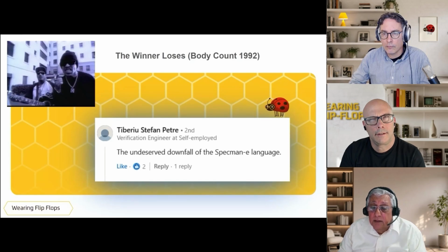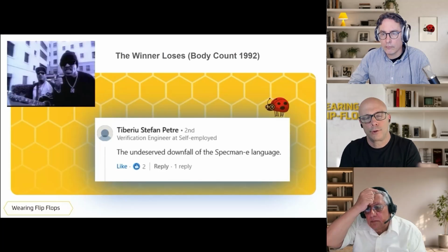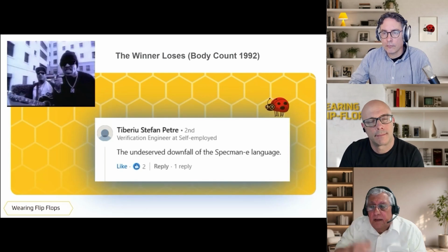Okay. And if we're talking about UVM, what do you need to do there in order to reach the same capabilities? There is a capability in UVM called factory, which is a pattern that a lot of languages use. You call a factory and you ask it to give you a copy of the extended struct type, and then use that instead of the original definition of the struct.